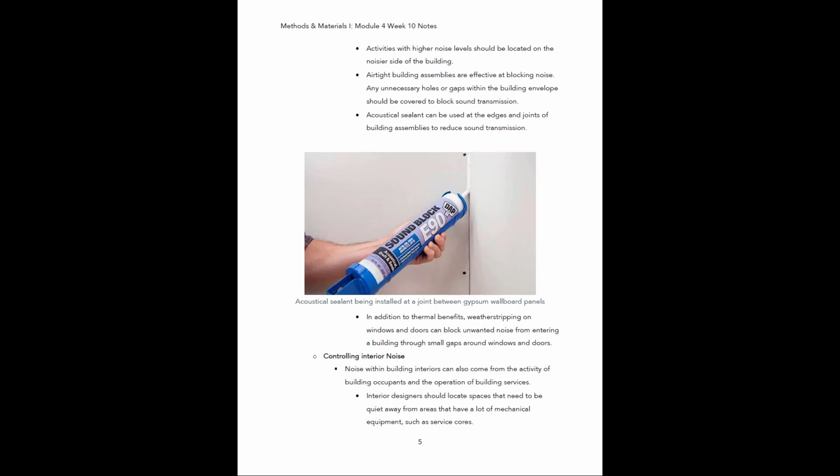So if there's a side of the building that tends to be noisier, maybe a busy street, whatever side that street is on is where you would probably want to locate those noisier spaces. And then maybe you have a childcare area or a nursery. You're going to want that to be a quieter space, so that would be placed further away from the noisy areas, okay?